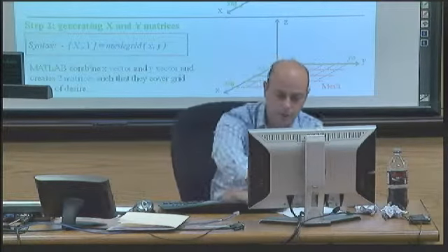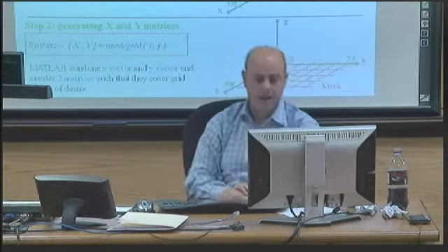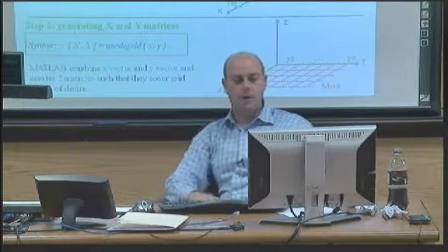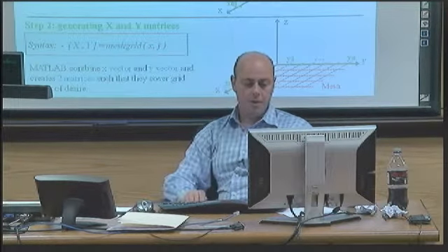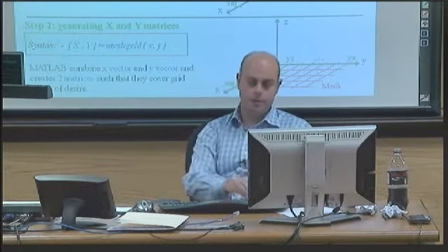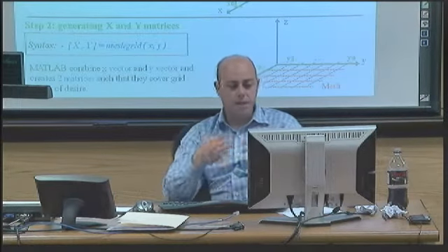So that's it all over here. For every x equal to 1, there are 20 different y's. When x is equal to 1, y is equal to 0, 1, 2, 3, all the way to 20. When x is equal to 2, y can be equal to 0, 1, 2, 3, all the way to 20. So it's on this grid, and we can use the meshgrid command to create that. The way meshgrid works is that if I've got vectors x and y, I'm going to use those vectors to create matrices which have the same information.